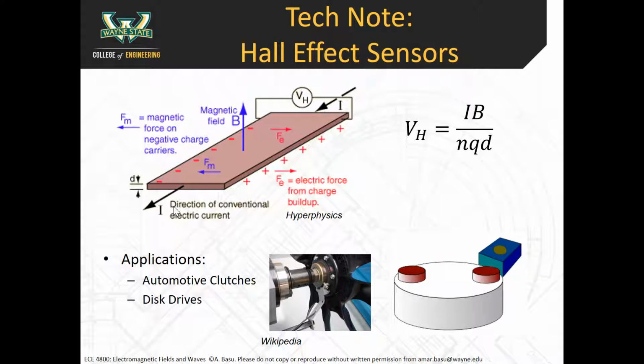And that's how you get this type of voltage that's formed. Okay, this is the magnetic force, the Fm. Again, electrons are moving into the page. First finger, magnetic field is going up. So your thumb is pointing from left to right. The electrons move opposite the thumb, so the electrons move from right to left. So it's in the direction of Fm, so right to left here.